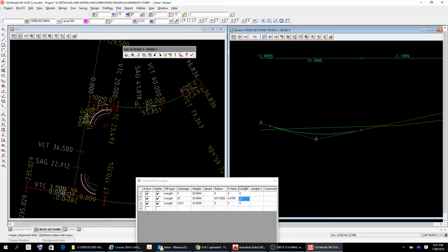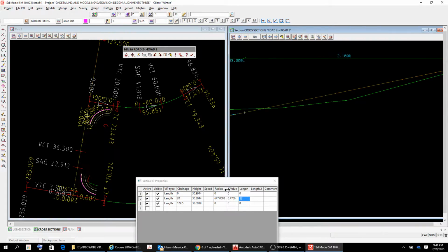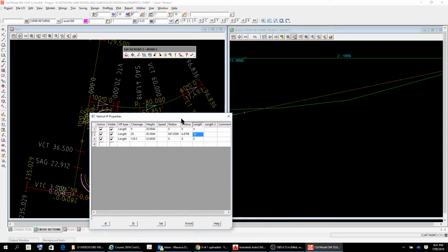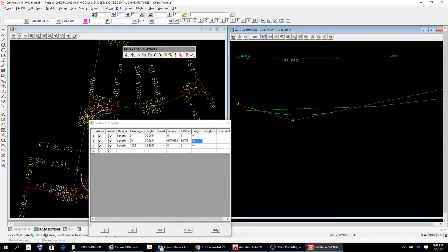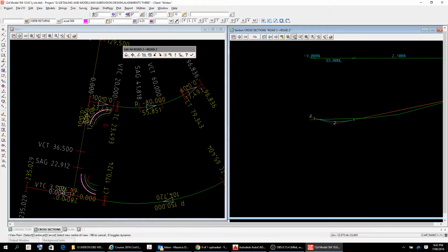I mean, it would be pretty easy to adjust that vertical curve there, but as you see, the K value of the vertical curve is starting to get a bit low. It could be a concern. But, yeah, we can adjust that there, but by not coming quite as far on the 3%, it raises things up. And that brings us now to our next curve.